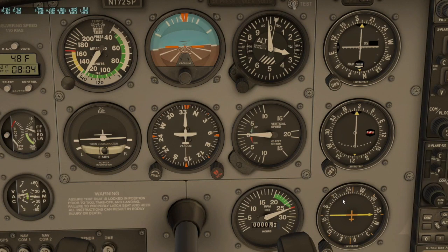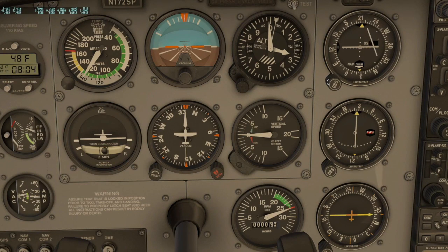So when I hit the next radial, the 220, I'm gonna go ahead and put it on the top. Here you go. Here's my 220. I'm gonna come at it with a 45-degree angle this way at the one I need to intercept, which is 250 inbound, and that is heading 025. So wait till the needle starts coming to the center. I'm gonna turn to heading 025 for the final step of intercepting 250 inbound.